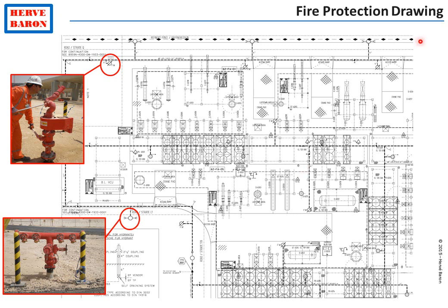This drawing shows the route of the fire water distribution network. It is a ringed network that circles the facility and is provided with isolation valves at regular distances, so that a part of it can be isolated and repaired without affecting the remainder.